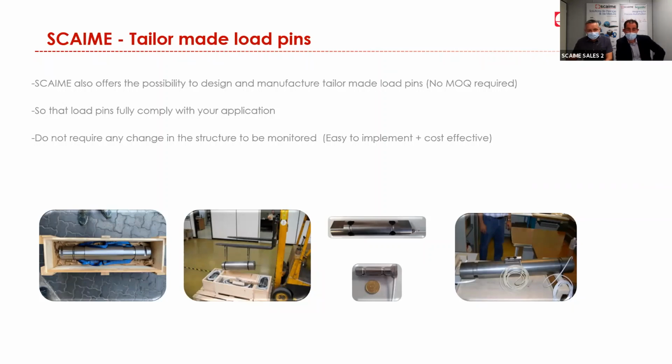Those load pins fully comply. The main advantage is that these load pins will fully comply with your applications and therefore will not require any change in the structure to be monitored. So this is very important because it means that it will be very easy for you to implement, because you will only have to replace an existing axle by the corresponding load pin, but also cost effective for you because there's no modification of the structure to be done.